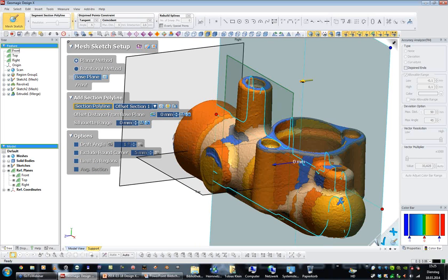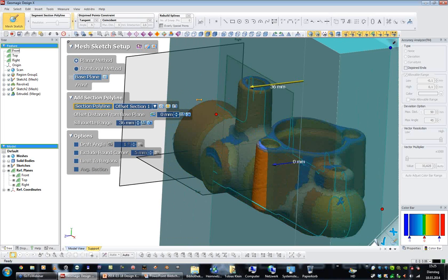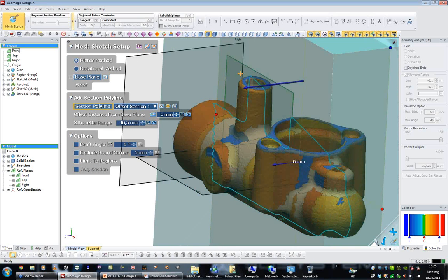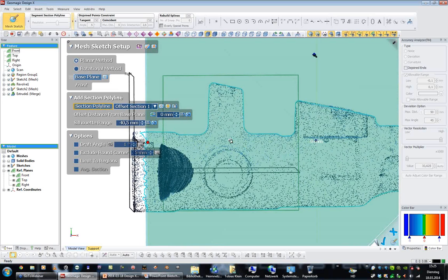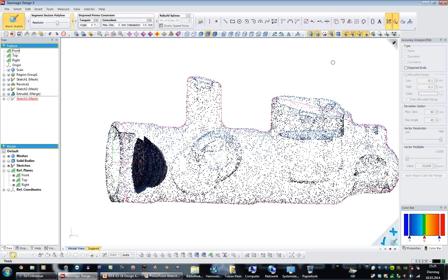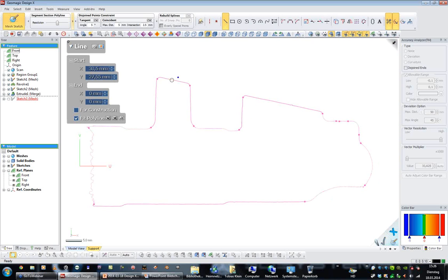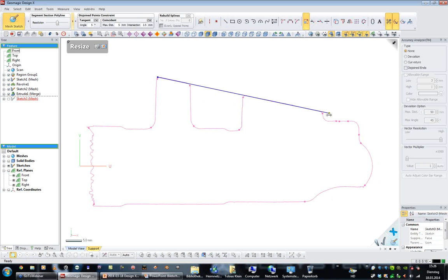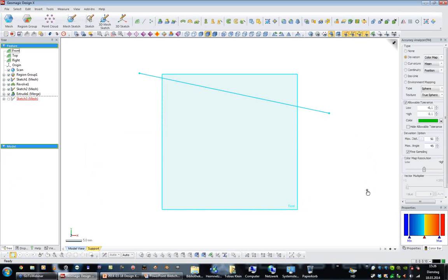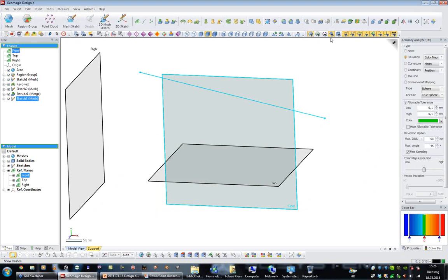But if we use a silhouette, then we project the whole outline of this part to the center line, which helps us to be more precise. So I can just click here and directly get this angle, and everything is much more precise than just picking 2 points.